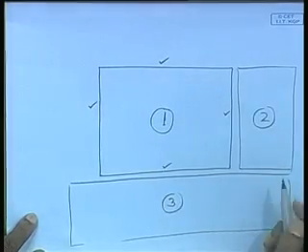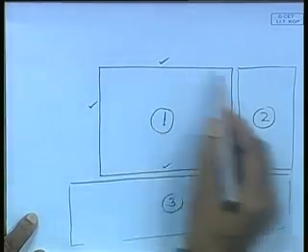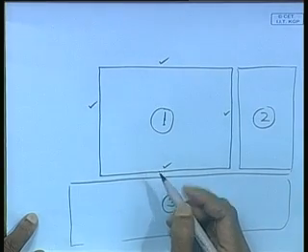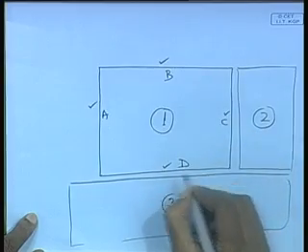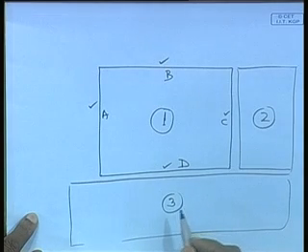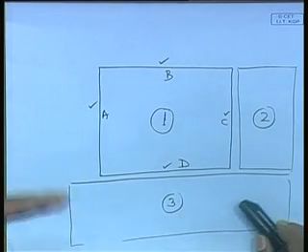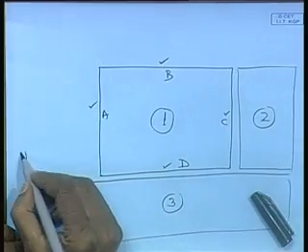So, how is it done? When panel number 1 is being fabricated, are all the edges finished? No, it is not like that. Say these are my edges A, B, C, D. The general practice is you keep any 2 edges finished. Finished means to the right design dimension. Say my D and C are finished.